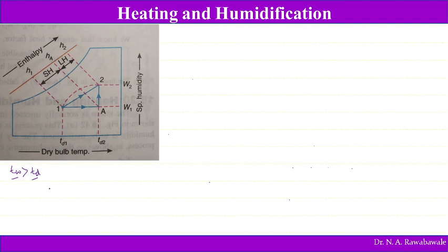When the air passes through water droplets having a temperature higher than the dry bulb temperature, the outer layer of the water droplet gets evaporated and mixes with the air, and the air comes out with higher specific humidity, whereas the water droplet is cooled.